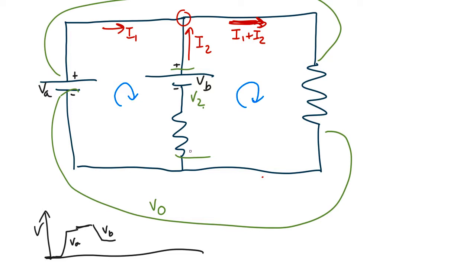And here, the current we've had flowing upwards, which means this must be at a higher voltage than that side. So it's going to go up. The voltage here must be higher, so it's going to go up by I times whatever this is. Let's call that RA. I2 times RA. Now right away, for consistency check, we can see this has come out wrong because the voltage here can't add up to what's there. So in this case, it can only work if either the current is going the other direction or if VB is bigger. Let's assume VB is bigger, so in fact it will go down to here and then go back up like that. So VB is bigger than VA.